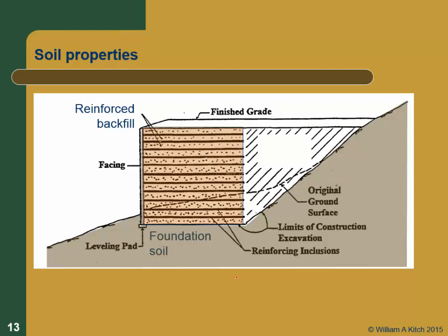The soil that's within the zone that's reinforced is reinforced soil. It's part of the wall. You really need to think about this as part of the wall. This is like the concrete in your concrete cantilevered wall. We're going to treat this totally different than we treat all the rest of the soil. All the stuff we were just talking about, interface friction angles and lateral bearing capacities, that's this soil we're talking about. That's the soil that you're going to use to build your reinforced wall.